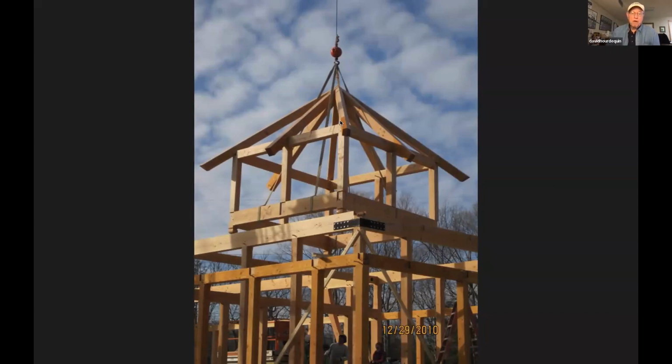In other words, if you don't restrain this diagonal hip member with screws to the post, then you can't develop the tension. So, but no, I don't do a frame analysis on that. And if you stop and think about most structures, it's easy enough to figure out a 2D frame within it that you can analyze.